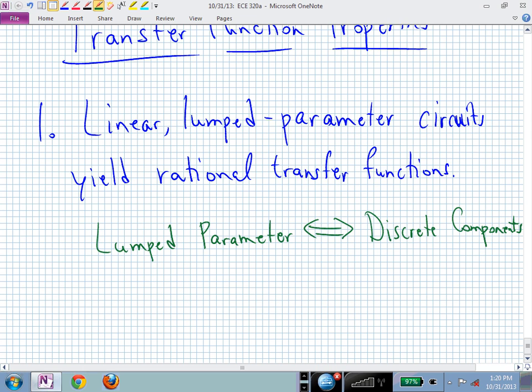So you can divide that out, and you'll find that the wavelength is quite long for 60 hertz, right? What's the speed of light? 3 times 10 to the 8, roughly, meters per second. Divide that by 60. That's not dividing by much, is it? What's your wavelength? What's lambda? On the order of 10 to the 6th, 1,000 kilometers, right? That's 1,000,000 meters.